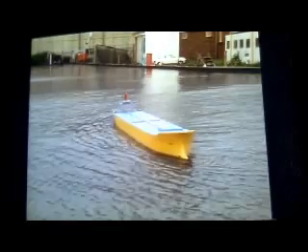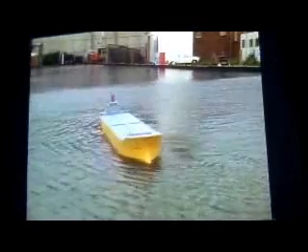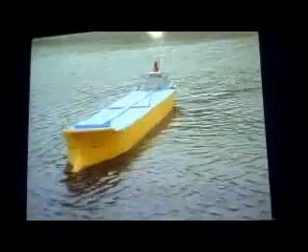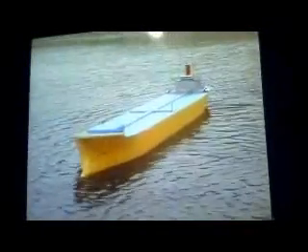At model scale, the action of the forces involved is studied in detail. The hydrodynamic effects are determined for a series of drift speeds and a variety of heading angles. The effects of trim and heel, although small, are also investigated. In the wind tunnel, aerodynamic forces on the exposed superstructures are established for a series of wind directions and for different conditions of heel, loaded and trim.